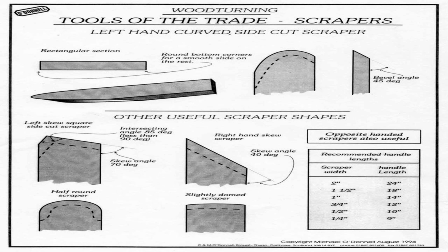The first one up here is obviously a curved straight scraper, and for the angle of the bevel, on here they recommend 45 degrees. In my opinion, that angle is not critical, as long as you cut back some so that you're not rubbing a bevel on the wood at all, because a scraper only uses that very top edge as a sharp area for usage in scraping.